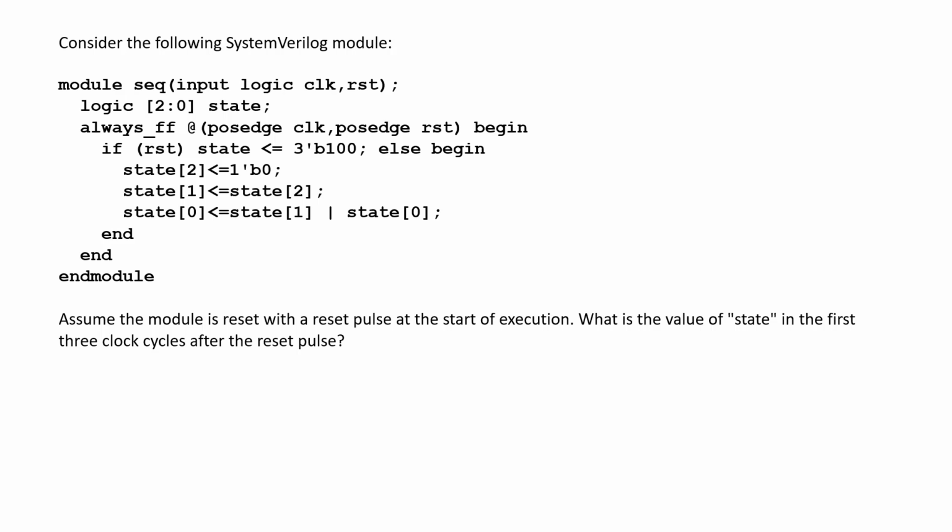And these variables, state, so this is the part that's a little misleading here. State is the current state, but when you're setting state, you're setting the next state, because you're using, in this case, non-blocking assignments. These assignments to state won't take effect until after you're finished evaluating the always.